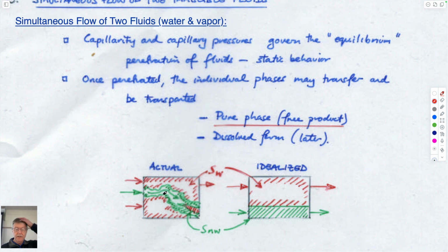So the system that we can imagine having is something like this, that we have flow paths that develop. It turns out that in this case, our non-wetting fluid would be green, I think, which would be air. And because of the capillary characteristics of that, the air will occupy the largest, continuous train of pores through the system from one side to the other, and the wetting fluid will be relegated to the smaller pores, the bottom of the distribution of pore shape.